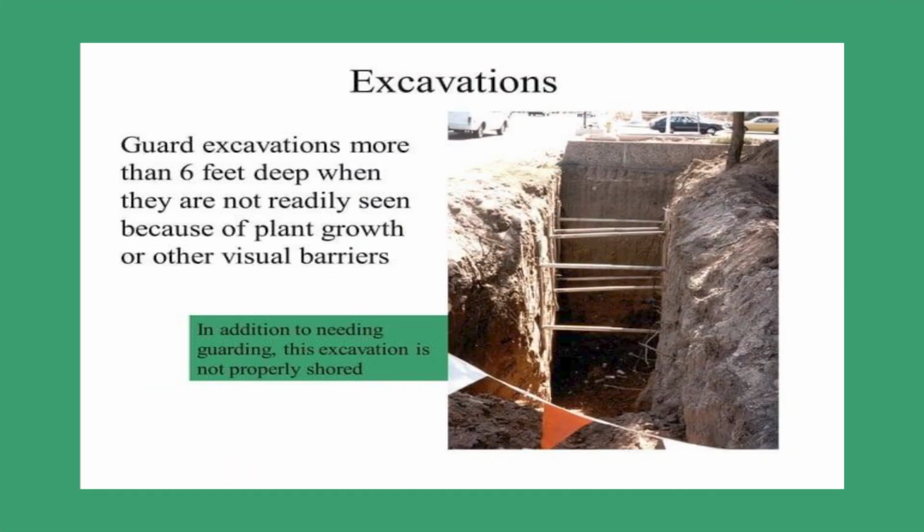Concrete form and rebars. Use a personal fall arrest system when working on formwork or rebar cover, or capping protruding rebars. Excavation. Guard excavations more than 6 feet deep when they are not readily seen because of plant growth or other visual barrier. Roofs. If you work on a roof and can fall more than 6 feet in height, you must be protected.